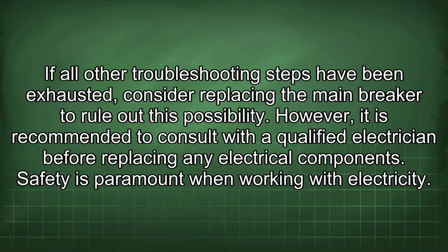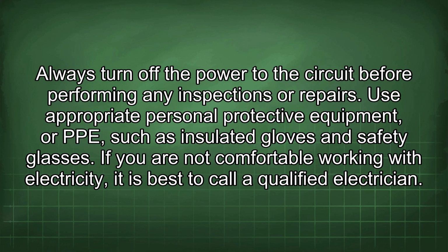Safety is paramount when working with electricity. Always turn off the power to the circuit before performing any inspections or repairs. Use appropriate personal protective equipment, or PPE, such as insulated gloves and safety glasses. If you are not comfortable working with electricity, it is best to call a qualified electrician.